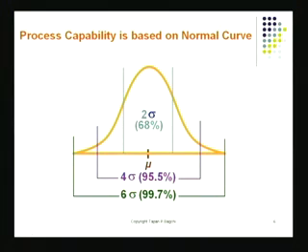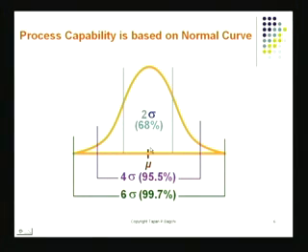Now, some other features also we utilize now. Once we've acknowledged that the process is going to be normally distributed, we do a couple of things. We can mark parts that will specify the exact area that will fall within a certain range, that is above and below the mean value.